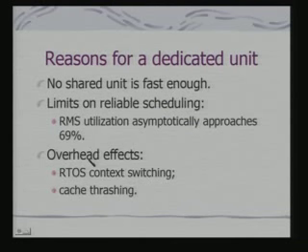Also, there are overhead effects. As I have told you, in a software platform, my RTOS kernel can be made use of for managing the concurrent model, but each task will correspond to a process in the RTOS, and there would be context switching. The context switching overhead can actually affect my timing constraints.